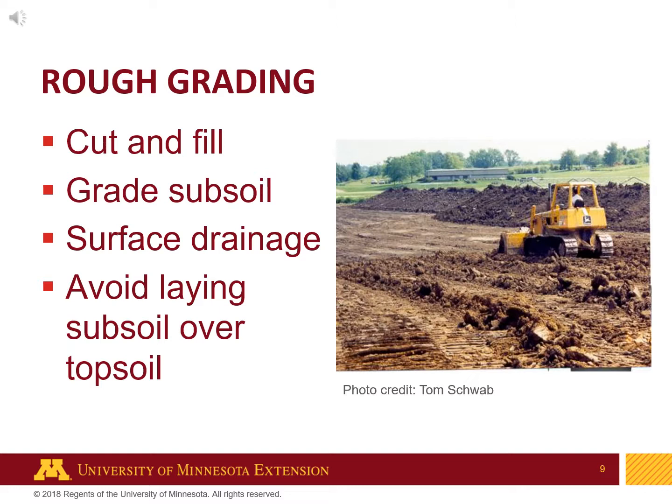Throughout the process, surface drainage is checked against the grade to prevent future problems for the site. Although it may be impossible to avoid in some roadside circumstances, you should avoid laying subsoil over topsoil.